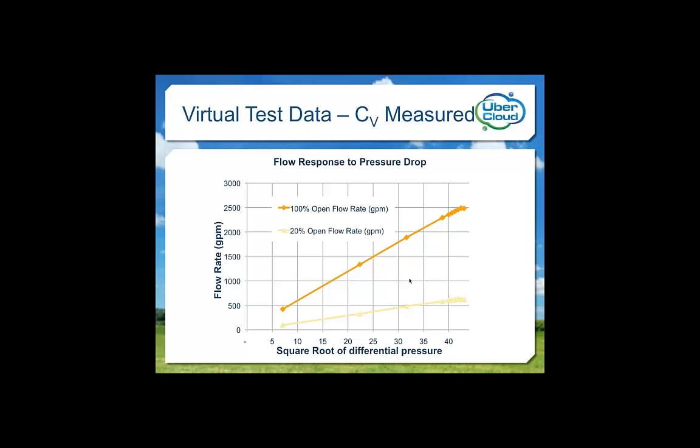To recap, I figured I needed 10 data points over the span of pressure drop settings for each control position. In the range of differential pressures that yielded fully developed turbulent flow, I just needed 3 or 4 data points, figuring that they would line up to represent C sub V. And the rest would be clustered in the higher pressure drop range to identify where the flow chokes.